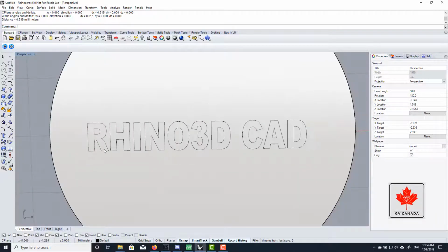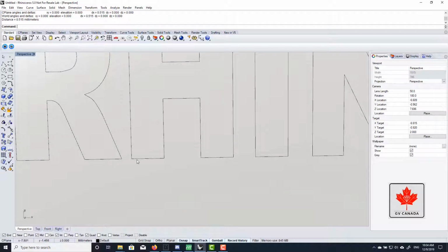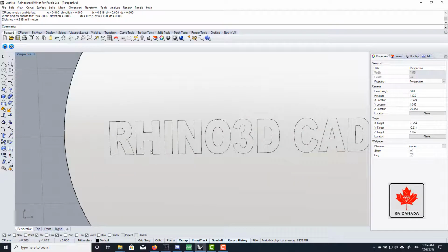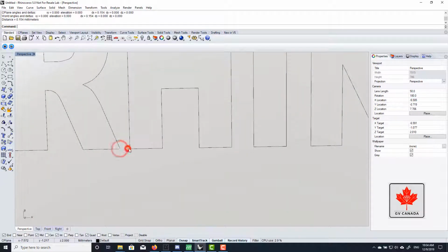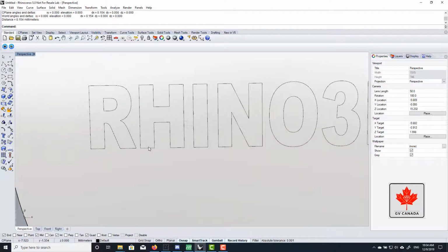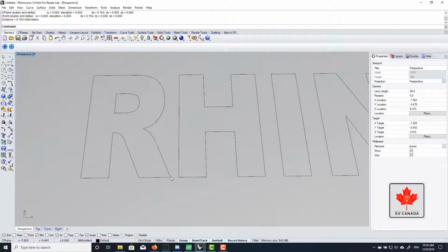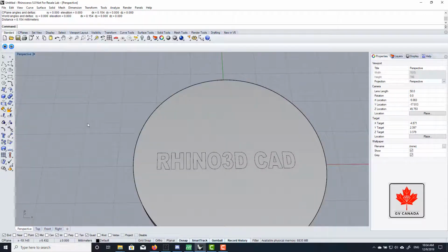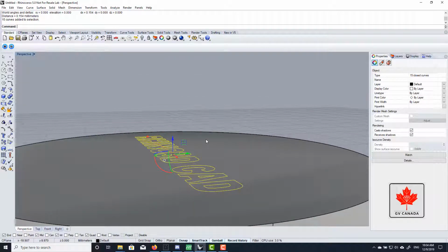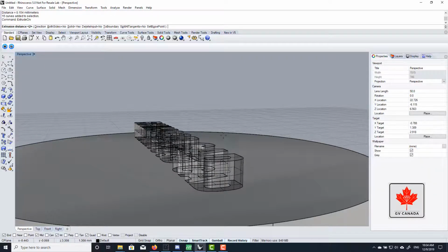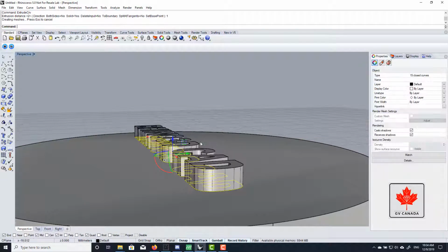Another thing is you also want to adjust the spacing here. They should be about 0.3 millimeters apart. This right now is 0.15. So depending on the quality of the printer, this may be fused. So this is like an extrusion. So if I type extrude, and then I want to extrude this above the surface. So let's say 1 millimeter above the surface.